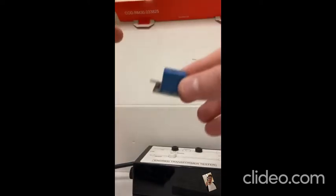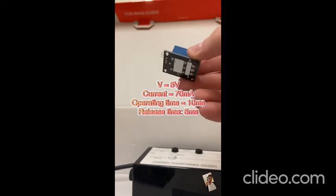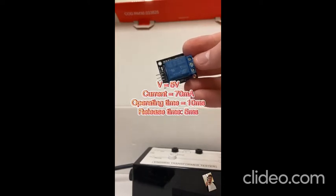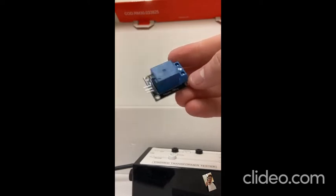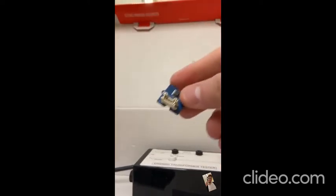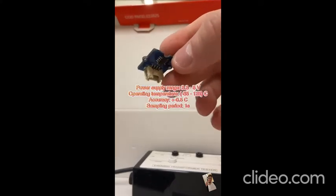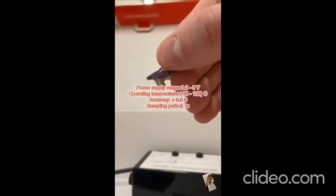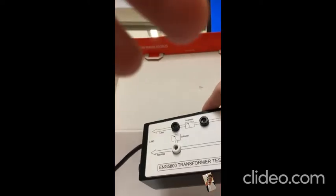And the second main component is the 5-volt relay. This is where I'm going to be controlling the switching on and off of the heater based on the temperature reading of the temperature sensor. And finally, this is the temperature sensor, which is going to be connected to the Arduino to measure the temperature of the room. And over here I've got my transformer tester.